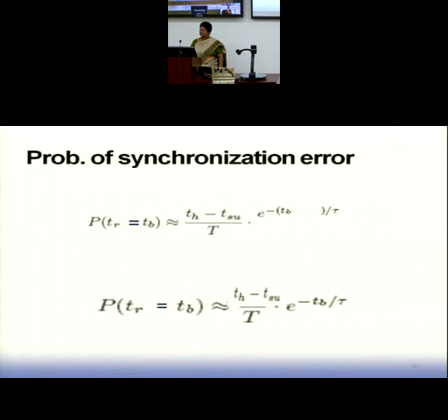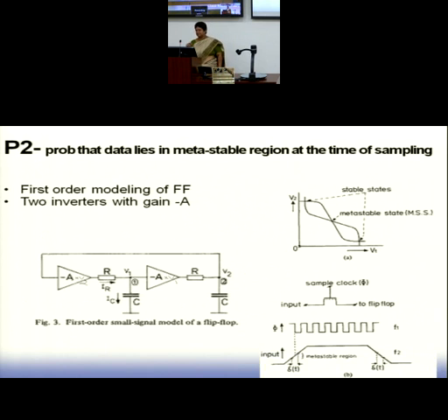So now let us see. Rabaey, as I said, ultimately your T setup and T hold actually relate to VIL and VIH. Your textbook, Rabaey, takes a slightly different approach. He tries to analyze your bistable element from the point of view of switching threshold, VIL, VIH, and then again comes to an MTBF expression. Ultimately we will see that when you combine and compare the two, they are actually the same.